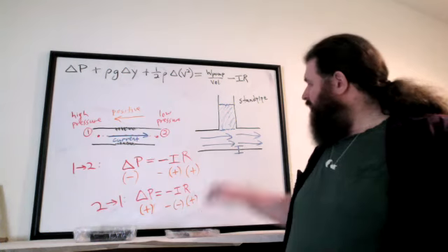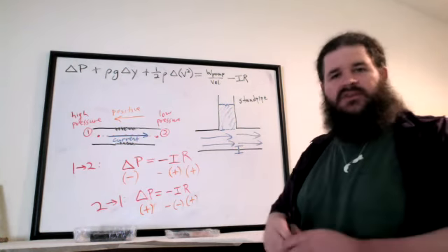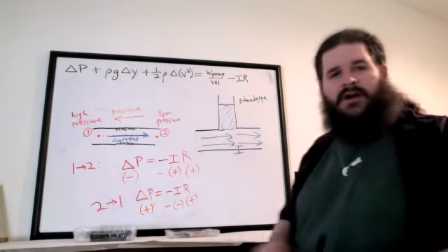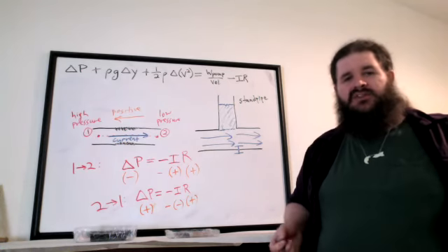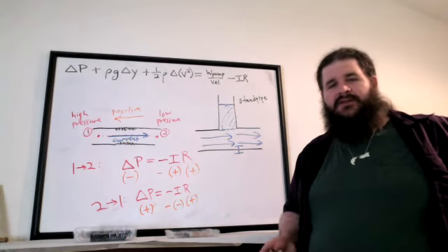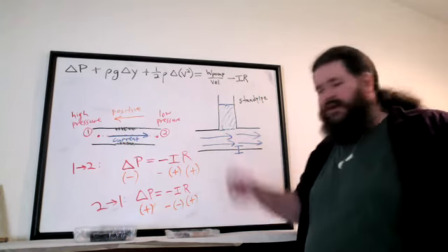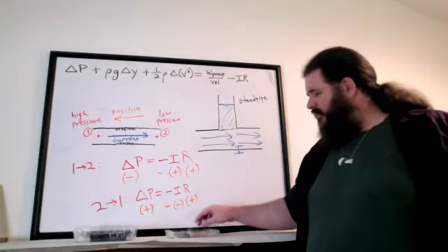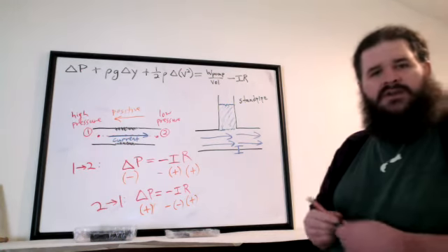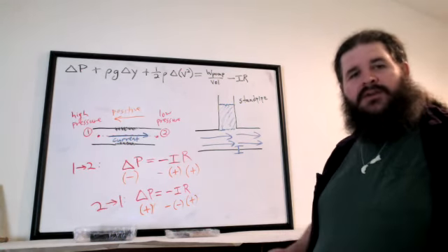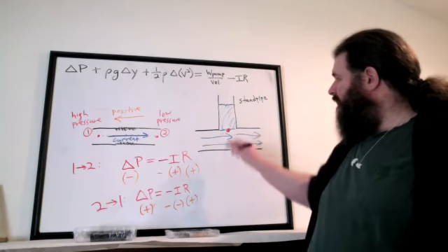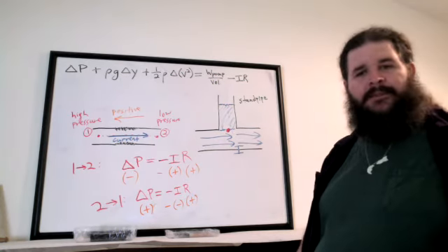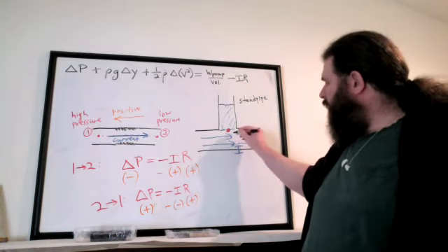And in that case, we have to treat these as two different fluid systems. The moving water and the stationary water have to be treated as different systems. Even though they're the same type of fluid, they're different properties. Moving versus stationary mean they're treated as different systems. What you can do, though, is as usual, you can mark a location at the interface where they're connected together. So let's say we call this point 1.